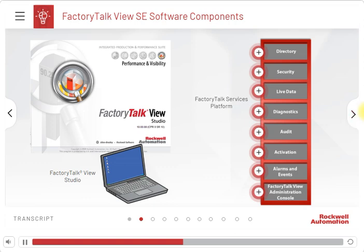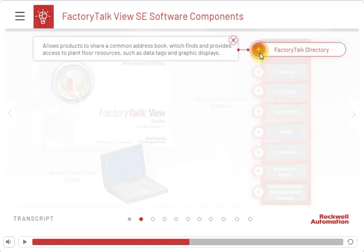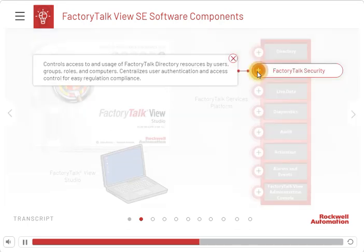The FactoryTalk Services platform. The FactoryTalk Directory allows products to share a common address book, which finds and provides access to plant floor resources, such as data tags, and provides a set of common services, security, for all the FactoryTalk products and applications used in a control system.